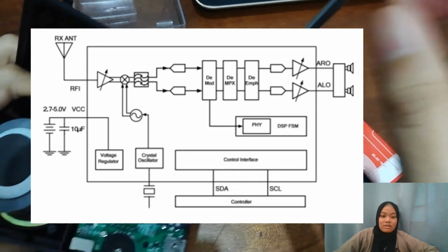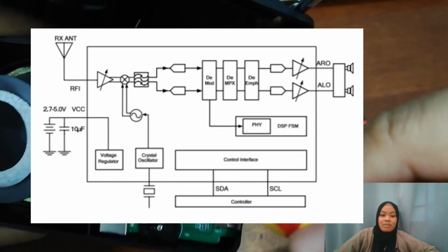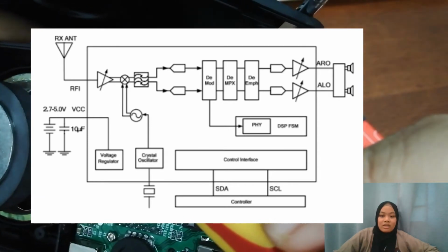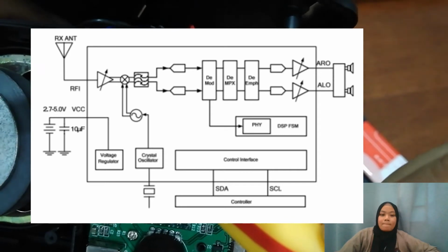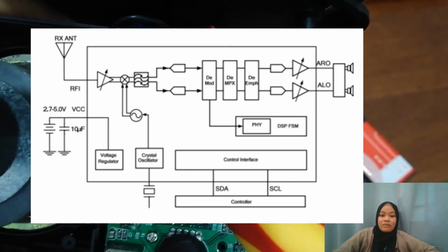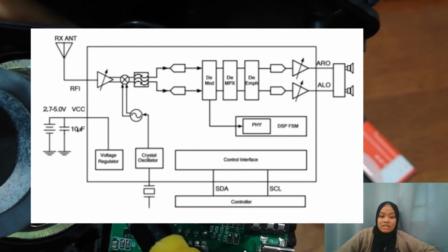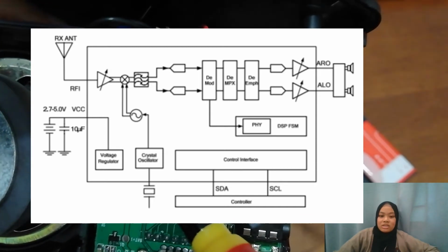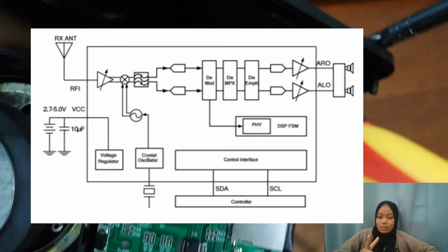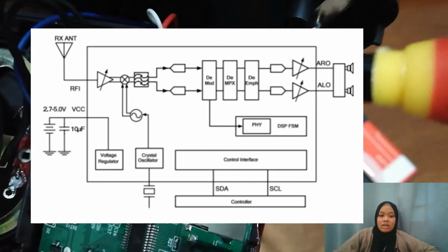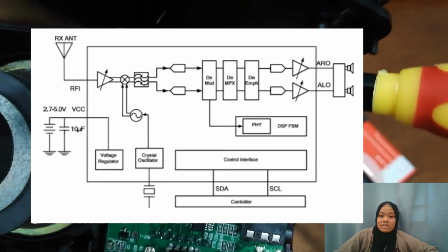The RF signal is first amplified by an integrated low noise amplifier, LNA, and then down converted to an intermediate frequency, IF, via a quadrature mixer. To improve image rejection, IMR, the quadrature mixer can be programmed to be at high side or low side injection. An integrated IF channel filter rejects out of channel interference signals.